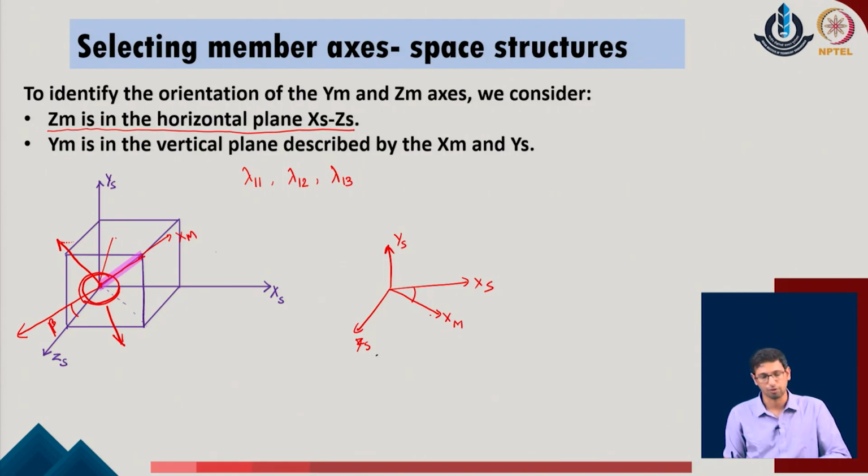Of course, this is not the final x of m, but as a first step I am trying to bring it, and then this becomes our z of m in the given system. So, that is the two understanding for the given system, and we bring it with respect to some rotation angle beta in the given problem. That is why we call them x of beta and z of beta in the given problem. So, with these two axes defined, we can now locate that y of beta will be again in the similar axis as it was defined earlier, and we can consider this case as a simple rotation about the structural axis y of the given system, such that the given xs and zs plane are rotated with the angle beta in the given system.